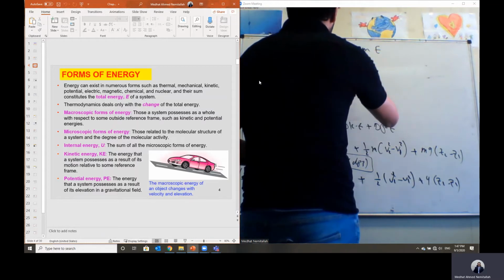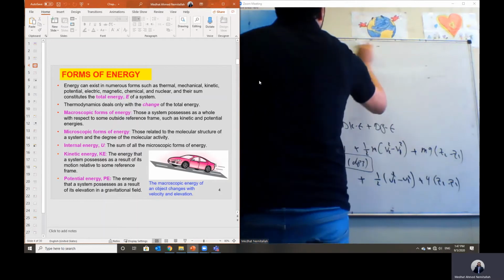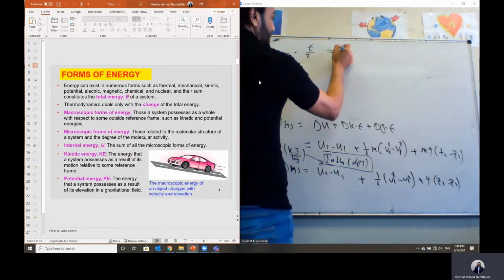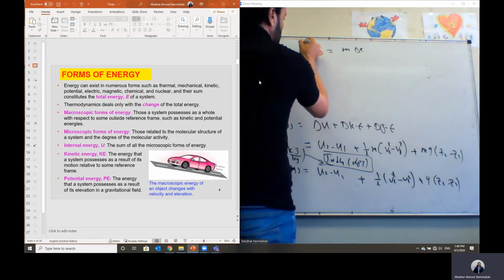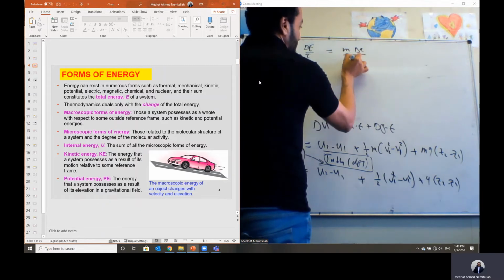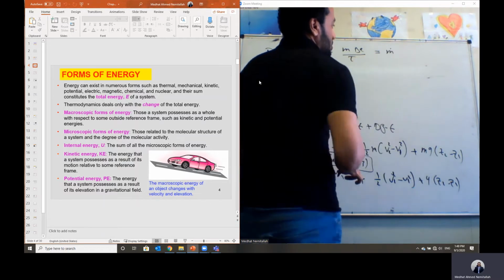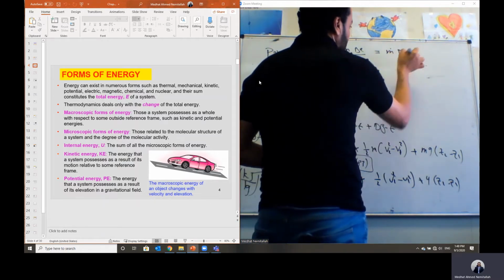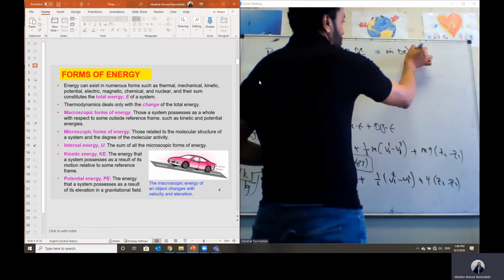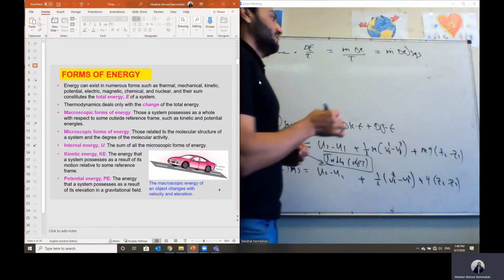It is the energy per unit time, and the energy is equal to mass, or the change of energy delta E per unit time: mass multiplied by the change of specific energy divided by time. And the mass over time we call m dot, which is the mass flow rate. So it will equal the mass flow rate, m dot, multiplied by the change of energy of the system. What is mass flow rate?